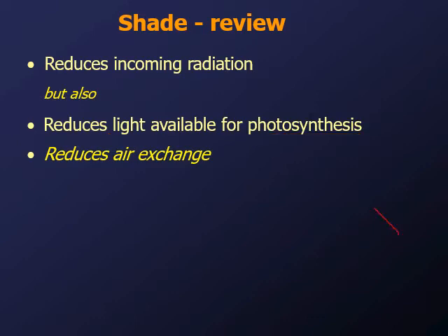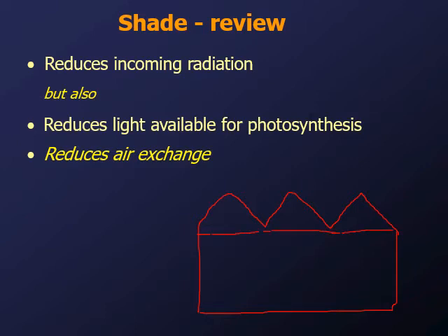So if this is your greenhouse, there's say a couple of peaks or gables, right? There's our greenhouse. And I have an energy curtain, right? And say it's hot and I close it all the way. There's lots of heat that's going to build up in this area here. And the greenhouse itself will stay cooler because it's shaded, right? But this heat here will also continue to radiate down. So it's not a perfect situation.